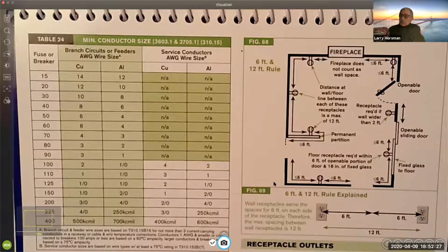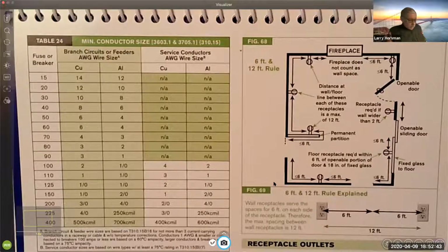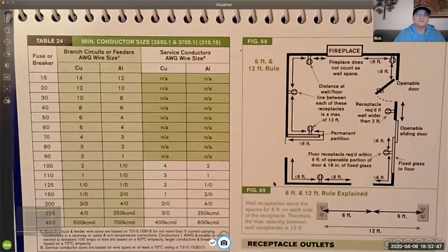That's an abbreviated version of table 310.15(B)(16). But they just have enough information there to cover residential type installations. That's the minimum wires one. Yes, table 26 in our book.